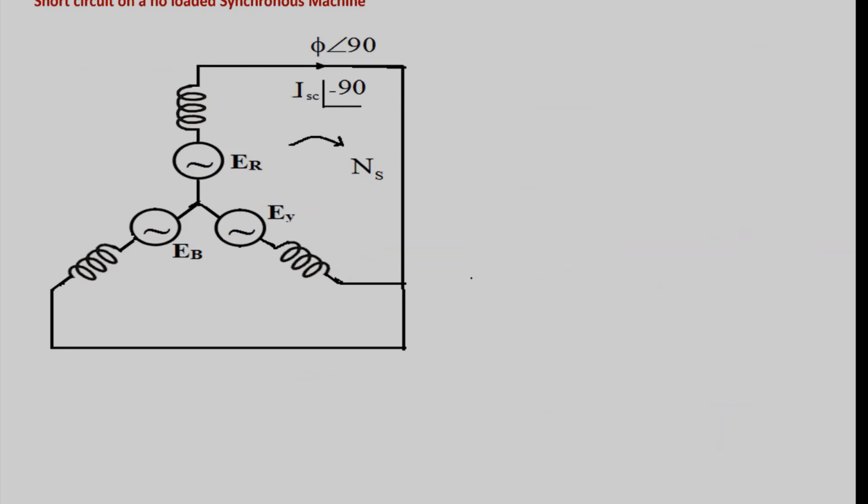When a dead short circuit occurs at the terminals of the alternator, that is, a three-phase short circuit occurs, then what will happen? We know the impedance limiting the short circuit current is only the reactance of the alternator. There is no resistor. So a purely inductive current will flow, which is 10 times the magnitude of the full load current.